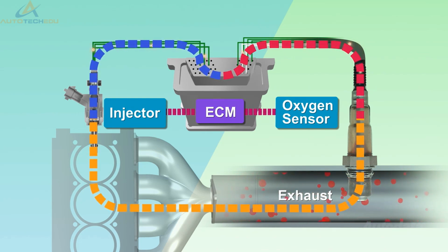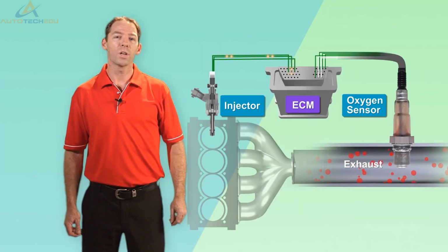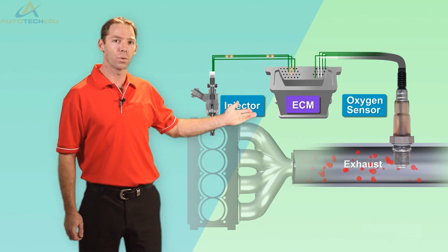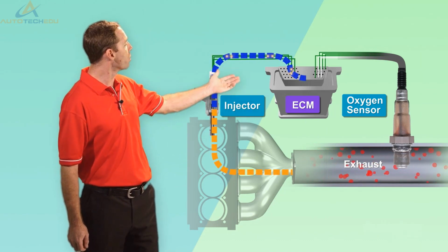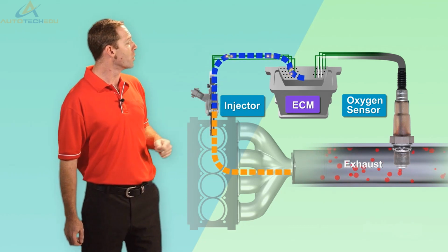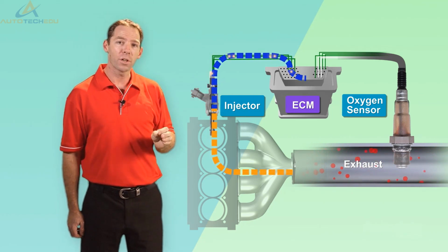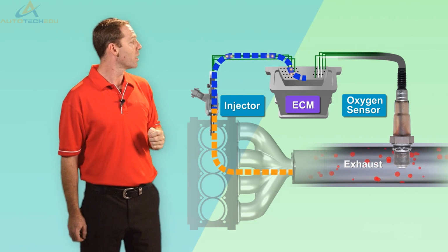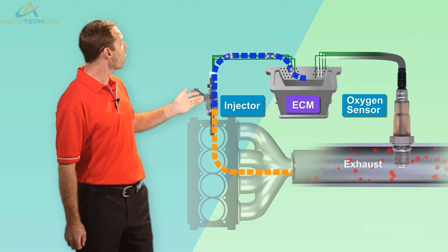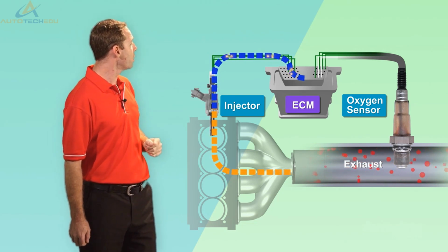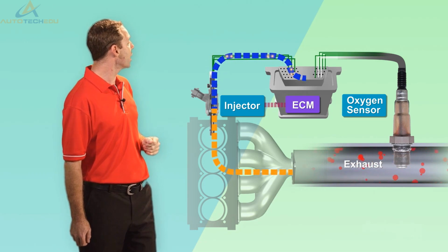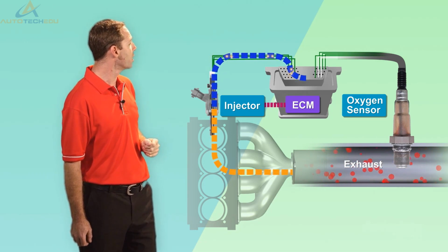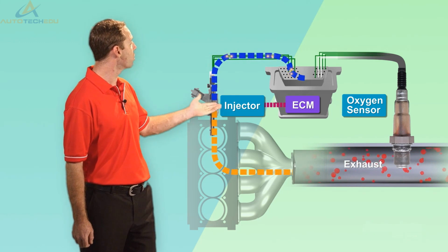has entered closed-loop mode. When an engine's oxygen sensors are cold, most ECMs will enter an open-loop mode. In this mode, the control loop is not a complete cycle, as the ECM does not react to oxygen sensor feedback. Instead, the ECM makes decisions based on pre-programmed information and various other sensor inputs.